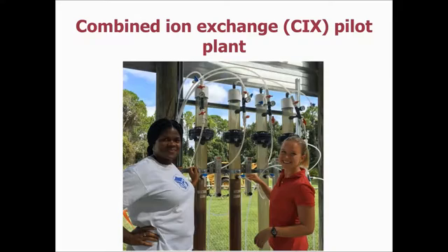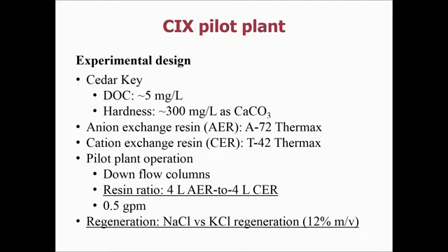So now I'll spend a few minutes talking about where we currently are with combined ion exchange. Currently we're doing several different pilot plant studies of combined ion exchange. These are the two current students, Jareen and Elise, working out at Cedar Key on some of the ion exchange pilot plant work. As I said, we're at this small drinking water plant. Right now, the DOC is on the order of about 5 milligrams per liter. It does vary somewhat because it's a shallow groundwater. And then the hardness is approximately 300 milligrams per liter.